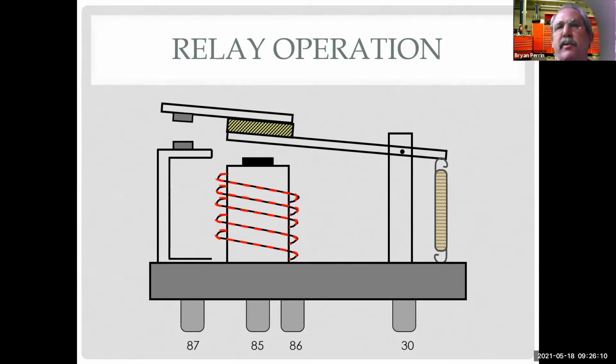So I'm still using the same amount of total power, but I now have two free ways to get there. And that's what we do on a car when we add fuses. I have the ability of going all the way back to the battery or putting another distribution box or another fuse box right off the battery. Then I can add more things because I'm not going to overwhelm my battery until I get really crazy with some super high-end stereo stuff, in which case we need a bigger charging system and a second battery. But for most stuff, all we're going to do is go back and pull another line up from the main, basically.